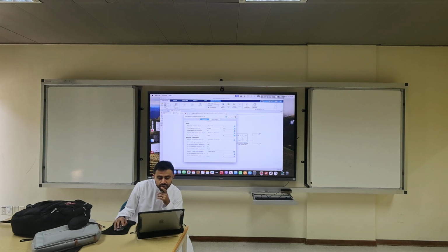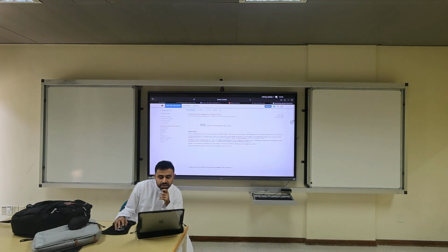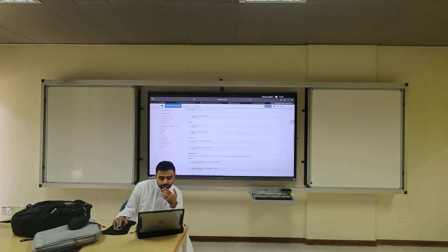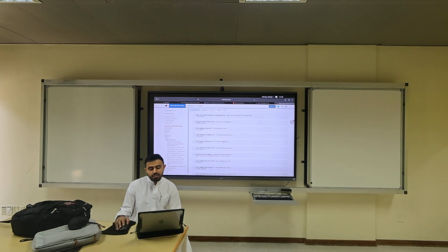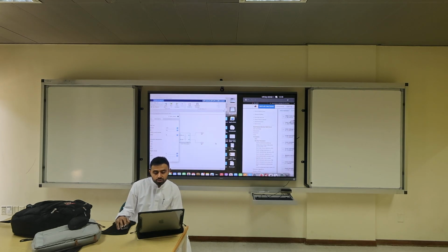This is the synchronous machine field circuit. So this is nothing but a circuit that applies a specified voltage to measure current through. What is its purpose? Its input is EFD, which is the field voltage, in per unit. And what's the output? The field winding, positive terminal electrical, negative terminal. This goes to the machine. And these are the parameters: rated, frequency, etc. So, homework 2, you will be exploring these.